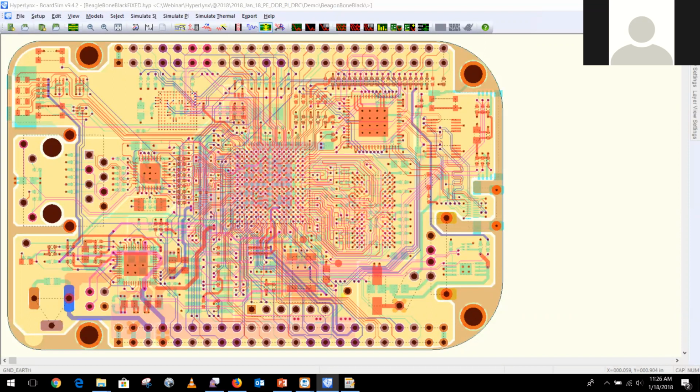Next question. Can we select only critical nets to check the ERC? Very good question. Excellent question. In fact, let me explain a little bit so you can understand. In simulation analysis, there are two ways to go about this: one is bottom up and one is top down. Bottom up means I have a design, I'm adding these 10 signals that are new, that are really fast and important. So I'm going to analyze those 10 or 20 or 30 or 5 or 2, whatever. Once I finish that, what else should I look at? Maybe I can look at this, maybe I can look at that. So you go from bottom up to the whole design.